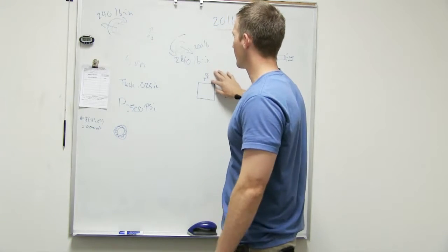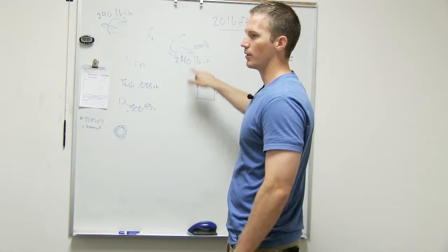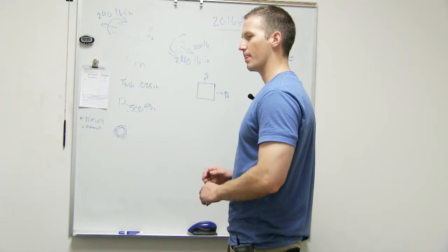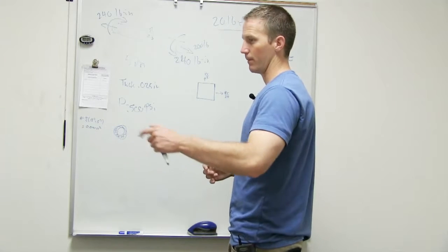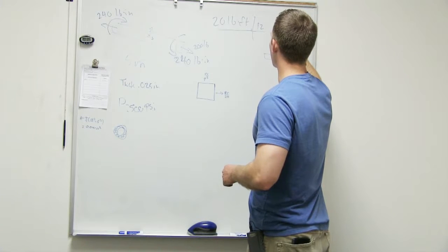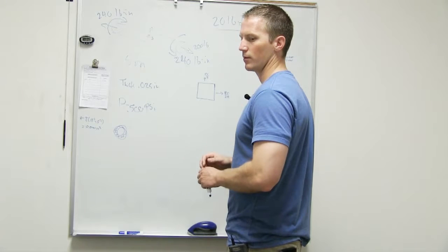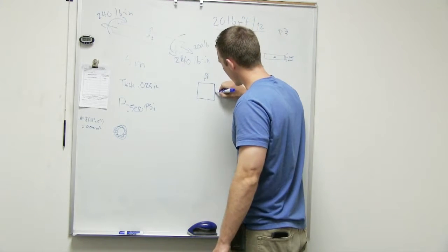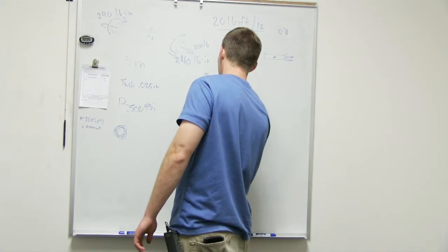That one's kind of by itself. The normal stress going this way also has the 200. So if I'm twisting this, I'm imagining that the 240 pound inch is like a shear stress on the outside of it. If you remember, internal torques create shear stress. So that's what that is. We're just going to say that that's acting down and up. So we'll just say that right there is the value of TC over J, and we'll calculate it in a second.